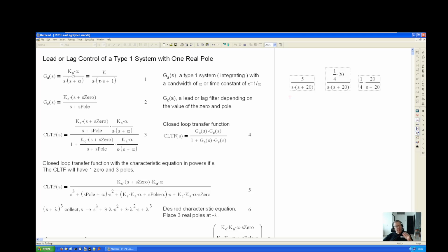And to relate that to the video that I'm critiquing, this is the open loop transfer function that was used. And she didn't say much about where these numbers come from. But again, this is a corner frequency. And then this 5 is the product of the open loop gain times the corner frequency. So a gain of 1/4 of a millimeter per percent output means that at fastest, if you output 100%, you'd only go 25 millimeters per second, which isn't very fast.